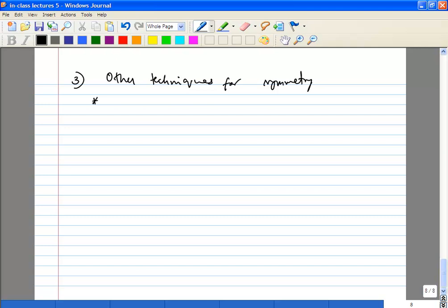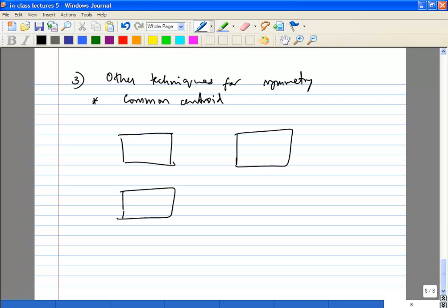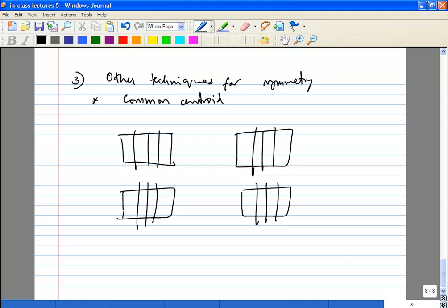So you can do what is called common centroid. Which is you now split the transistor, and you can combine all of these things. For example, you split it into 4 sections, and each one of these can be interdigitated. So this common centroid can be used in conjunction with the previous technique.